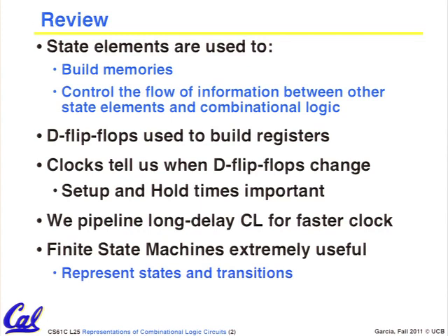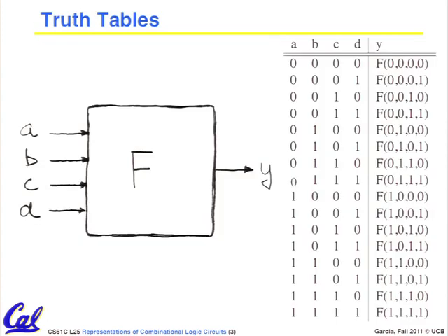We saw that example. So if we have a truth table, you're going to see a connection between finite state machines and combinational logic and truth tables at the end. In fact, on your last slide, you'll see this wonderful picture that shows the 3. So truth tables are important when we're talking about combinational logic. Today is about combinational logic, so none of the issues of state or timing really come in here. We're not going to talk about timing anymore in this lecture. Let's just talk about pure logic. This is just the fun part. This is the part that's totally digital.